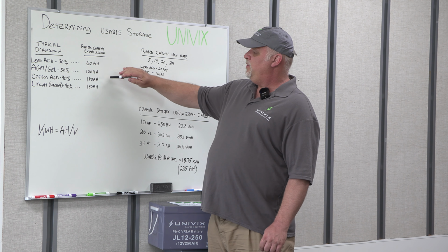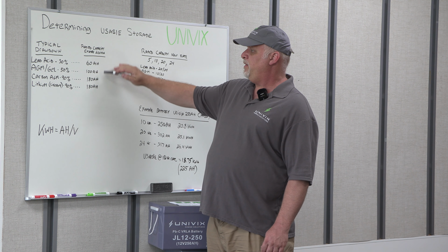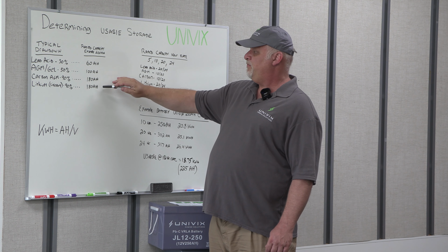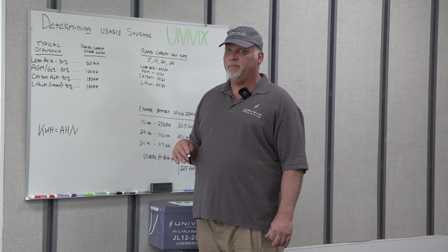So that means if you wanted to do a direct comparison cost-wise between a carbon or a lithium and a lead acid battery, you would have to buy 3 lead acid batteries for every carbon or lithium battery in order to have the same capacity in your system.